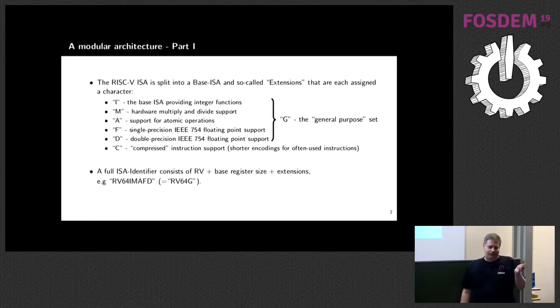And if one wants to specify which bits of the ISA a CPU supports, you get an ISA specifier like you can see below. IMAFD is G. When the Linux distributions started porting for RISC-V, we had to decide whether to assume the compressed extension as available or not. That had some discussions at that time. All the binary distributions that are working on RISC-V support right now assume that the C extension is there. There is work on a platform specification which defines that all RISC-V Unix-style platforms shall have the C extension.